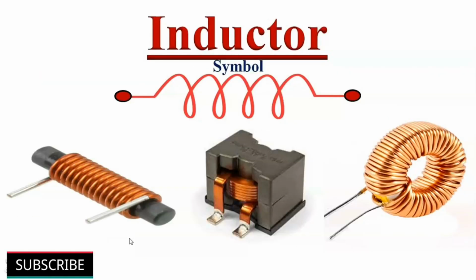Inductors' ability to store energy in magnetic fields makes them vital components in modern electronic systems, enabling efficient energy transfer and management. Filtering with inductors. Function. Inductors can act as filters by allowing low-frequency signals or DC signals to pass through while blocking or attenuating high-frequency signals. This behavior is due to the inductor's property of increasing impedance with increasing frequency.